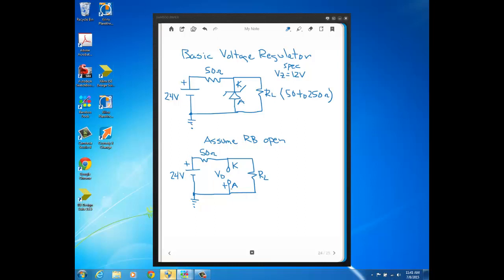Now one thing that's definitely true is that with the Zener diode connected in the circuit, as you see, there's no way the Zener diode could be forward bias, because the anode's attached to ground, which means VA is 0 volts, and remember diode voltage VD is equal to VA minus VK. So we're going to have 0 minus some positive number, because VK, that's the voltage at this node here, with respect to ground. And since the negative side of this voltage source is grounded, VK has got to be a positive number.